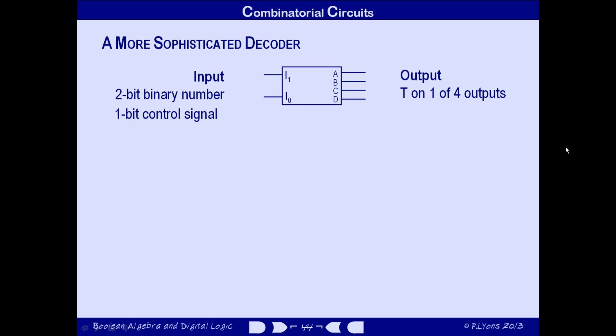Now, decoders are a standard component of memory chips. They convert a binary number that represents an address into an activation signal for a particular word in the memory. Well, the address wires always have some value on them, even if nothing's driving them. So, to prevent the memory from being activated at the wrong time and reading from or writing to arbitrary locations, we redesign the decoder so that we can explicitly force all of its outputs to be 0, irrespective of the value on the data input. That way we can ensure that the controlled devices will not be activated unless we want them to be.